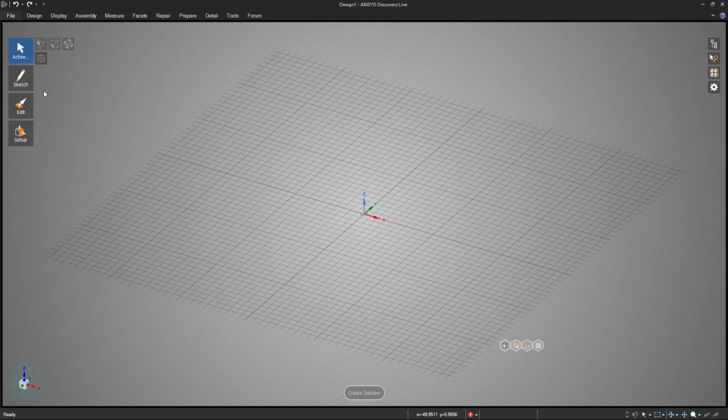To draw this, I'm going to start with the sketch tool, selecting the circle for the cylinder base. It's always nice to have your design symmetrical around the origin if you can. When I start to draw out my circle, you're going to notice right away that the units indicated in the blue box there are in millimeters, and everything that we had was defined in inches.